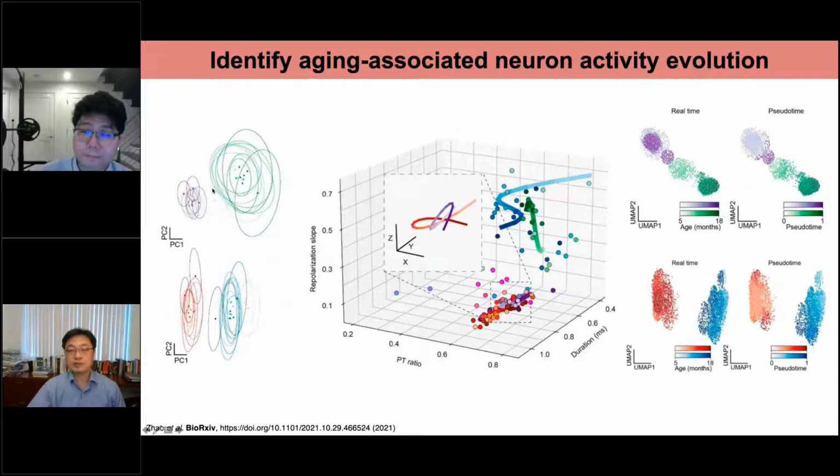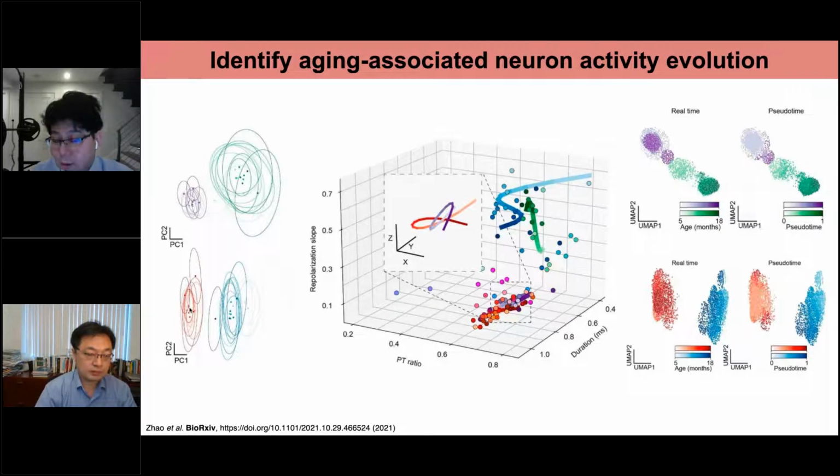We only consider signals where each electrode captures only one neuron, because for each electrode there are multiple neurons you can collect, and you use spike sorting to isolate them from one another. Among all the neural activities captured by the same electrode, we can see one neuron that shows a very stable electrical property, which suggests that the electrical probe to brain tissue interface is not degrading over time.